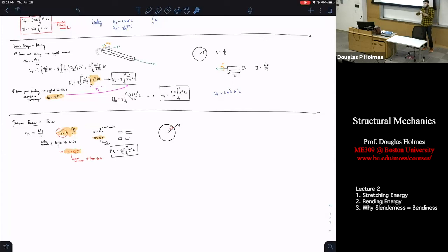Is gravity there in your model or is it not? More subtle ones are things like, is there a perfect connection between the wall? Is there some friction there? How is that moment that you're applying perfectly distributed along the edge, or is it really applied at a point and you're kind of approximating it as being uniformly distributed?